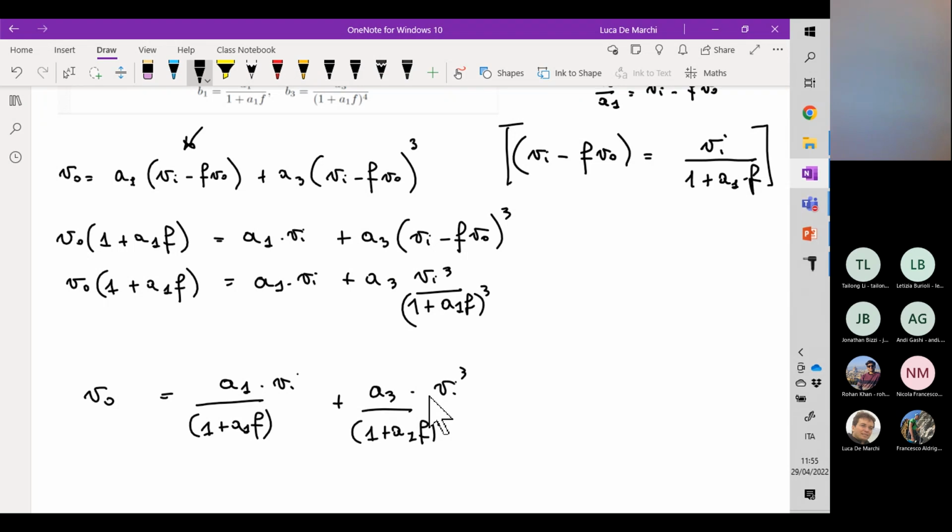At this frequency, which we will call omega null, we have to check this quantity here, that is the summation of the phase of the loop gain at this specific frequency plus 180 degrees.